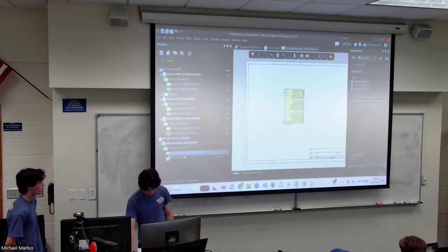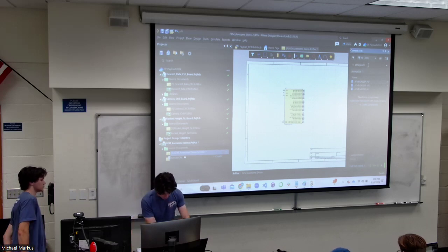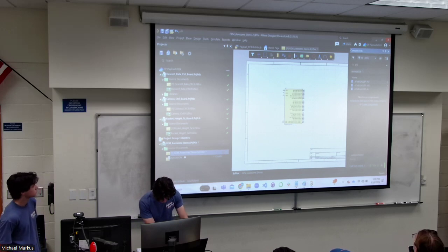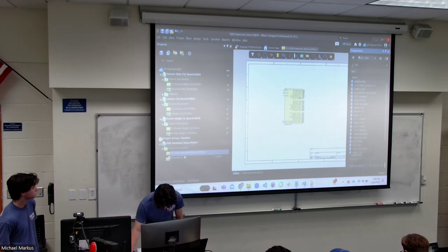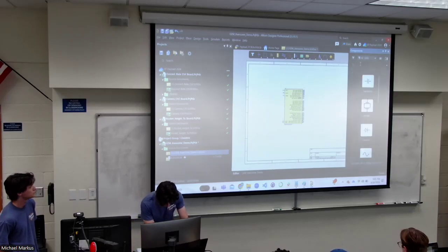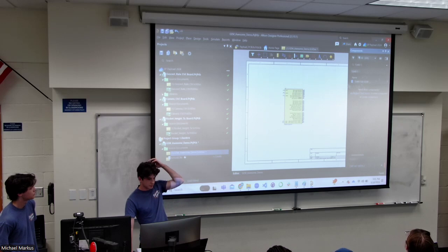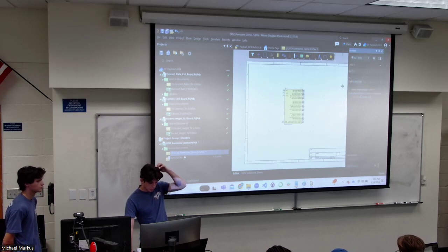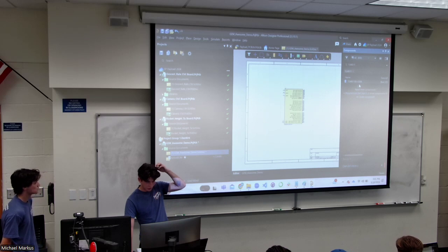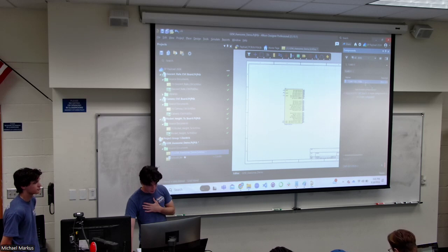We're going to need a few more components. We're trying to drive an LED here, so we need the LED, which I'm going to pick. If you just type in LED, or actually, this is the one I found earlier. We're going to do TLMB1100. It's this LED. This thing has a forward voltage of 3.9 volts, and this circuit would actually work in theory if you were to make it.